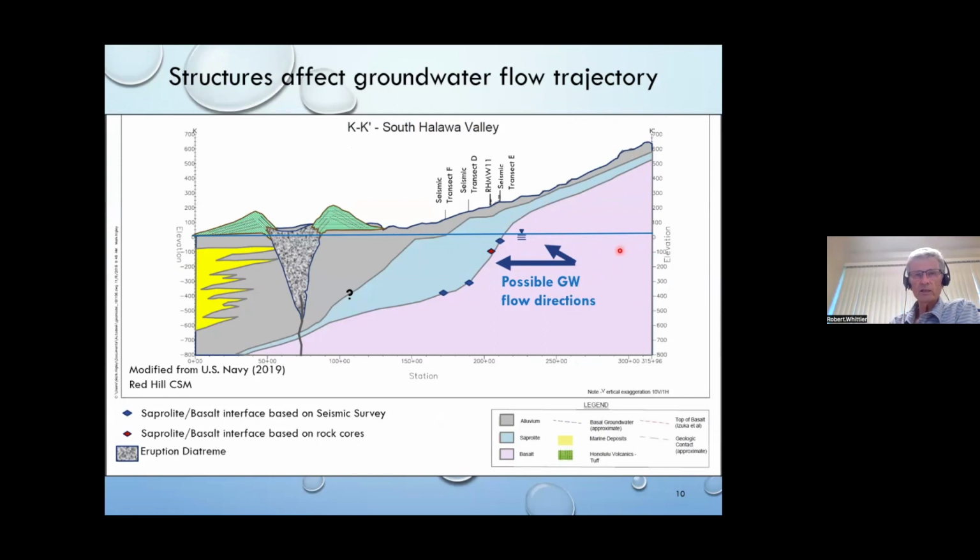If groundwater flow is Maui, it will go from the permeable basalt and then encounter the low permeability of the saprolite and the valley fill, and in some cases also encounter the subsurface structures associated with the late stage volcanics. Finally it would encounter the caprock, again generally viewed as being poorly permeable, but can have zones of high permeability, such as reef limestone layers and associated dissolution channels.